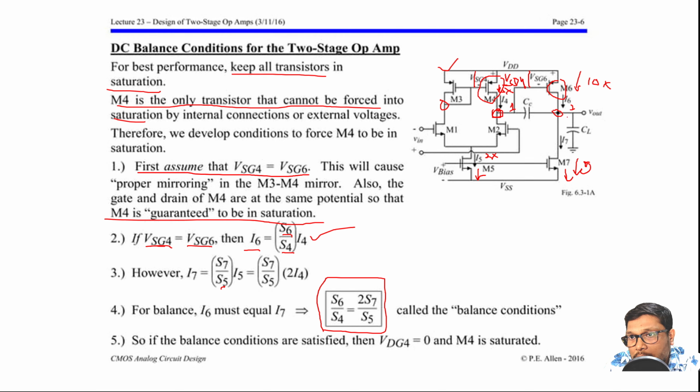From these 2 points, point number one, the input side, will take more time to charge, so we'll consider the minimum of this slew rate. This one will be the minimum, meaning this will take more time to charge this capacitance.